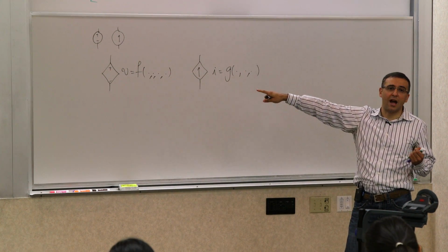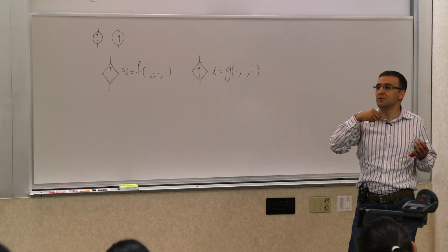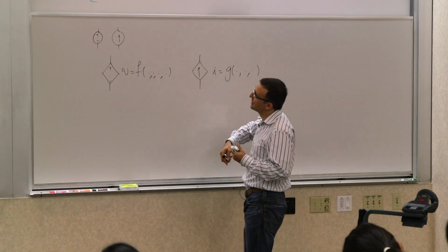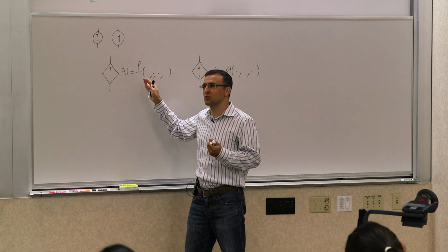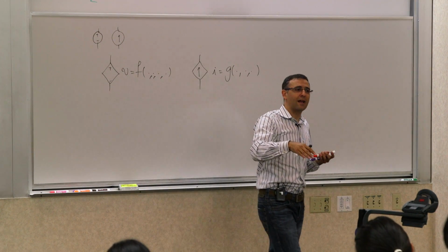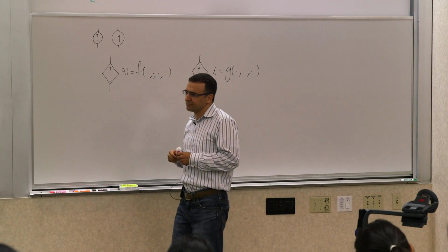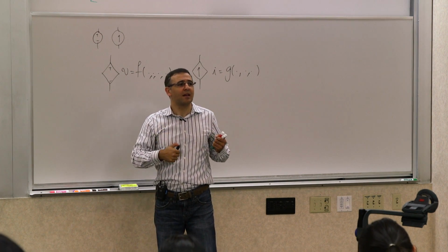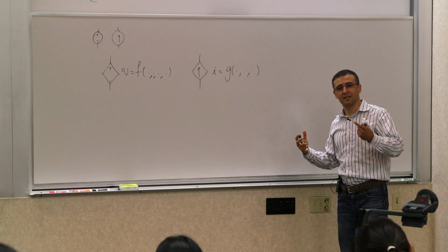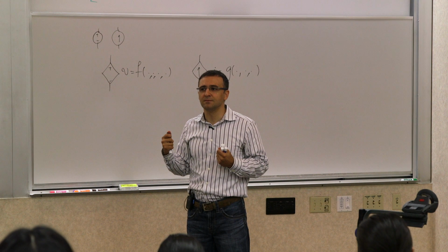So when you see one of those diamonds, it means that it's a dependent source. It means that it's not independently set. And you will see they're treated very differently, and they behave very differently. These dependent sources, there are 4 special cases: a voltage-dependent voltage source, voltage-dependent current source, current-dependent voltage source, current-dependent current source. And again, all of them are a special subset of all of the combinations you can have. But you will see they're useful in modeling things like transistors, things like the 3-terminal devices. All of those things can be modeled with something like that. Any questions?